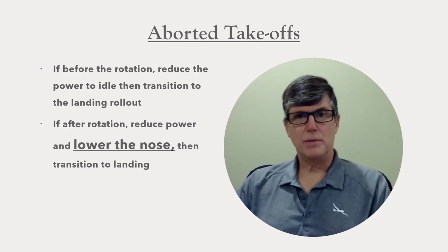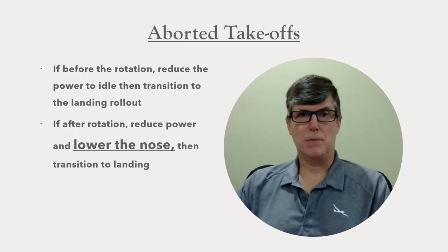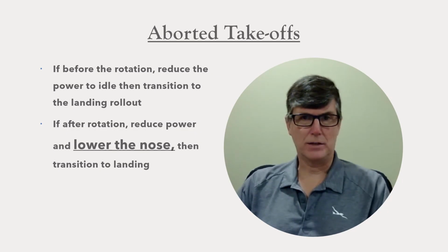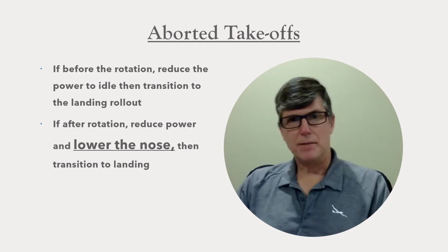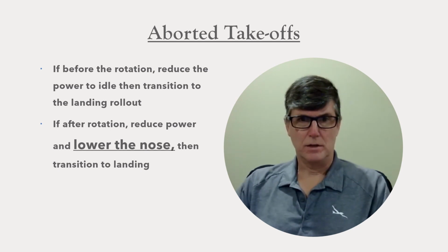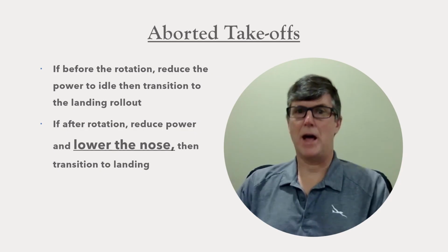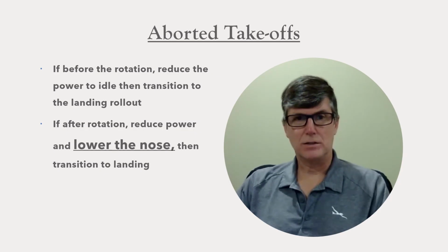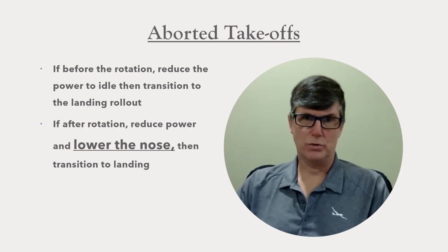At some point you may have gained enough altitude that it might be possible to make a 180-degree turn back to the runway. That maneuver has been called the impossible turn because a lot of people have attempted it and have stalled and spun. So unless your options for doing anything else are really bad, then turning back to the runway is probably a bad choice.